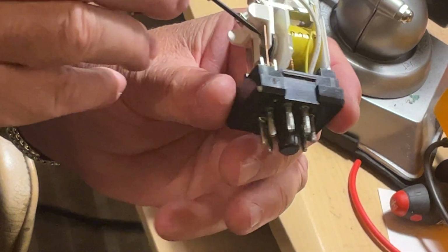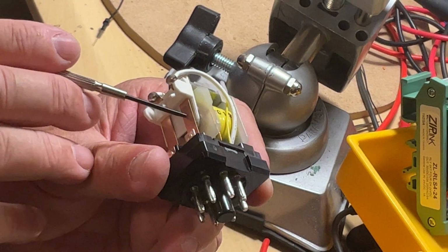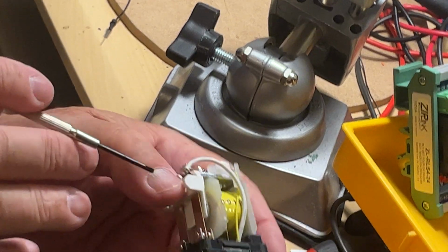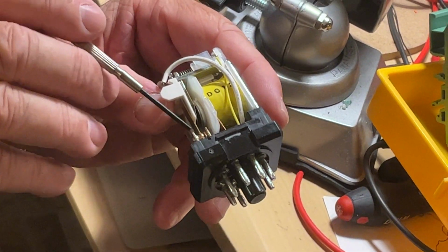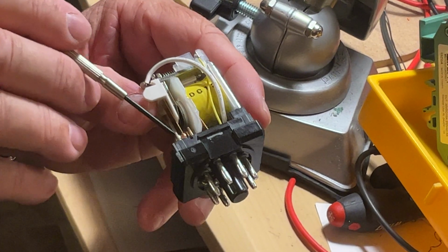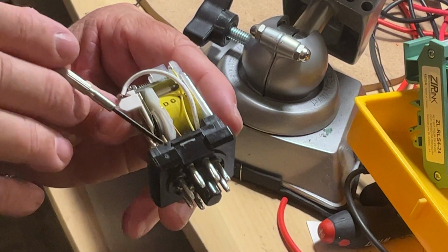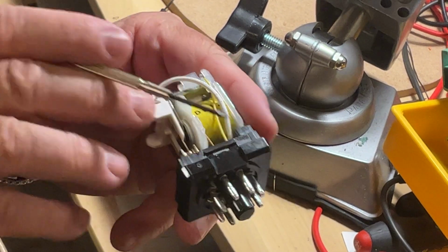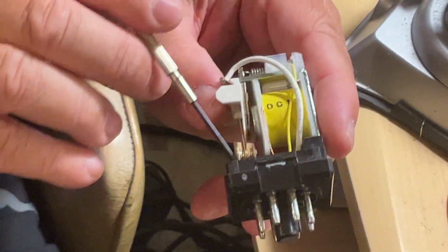The second part is made of the contacts. Here there is a long plate, this one. This is called the pole. And this is the actual moving part of the contacts, because you can count here one contact on my right, one on my left, and the long plate in the middle. When you do nothing, you don't energize the relay yet, the plate is touching the contact on my right.